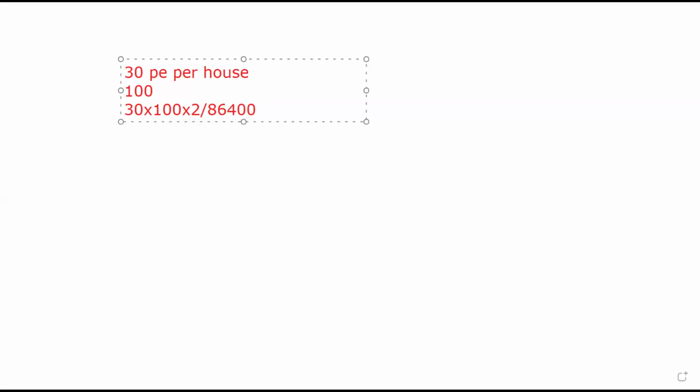Sorry, please. You said 2 suspended floors? Yes. That 2 suspended floors comes in when we are deciding which floor you will use as your reference. You cannot have 30 people in a plot if it's not 2 suspended floors. So the issue of 2 suspended floors comes in when you are doing your pressure losses. You consider the person at the uppermost floor because that becomes your reference. If you are trying to elevate your tank, you don't use the person at the ground floor; you use the level of the person at the second floor. If I ask you the elevation of the place, you will not give me the elevation of the ground floor. You give me the elevation of the person at the last floor.